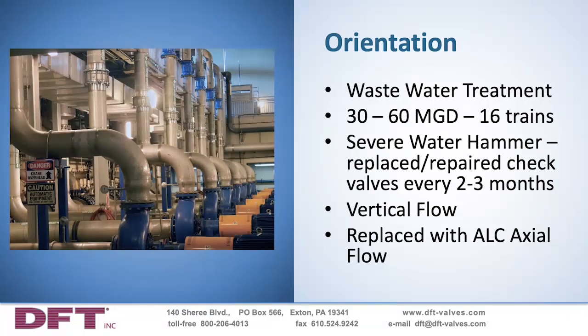Low flow can oftentimes be a problem where you've got pumps that are operating at a low flow condition by design of the plant. And the outcome of that is that the check valves that are in that system may chatter, and if it's left unchecked for a long period of time, will eventually fail. When that failure happens, it's possible for the internal pieces of the valve to break off and travel down the pipe, and then do damage to other pieces of equipment.